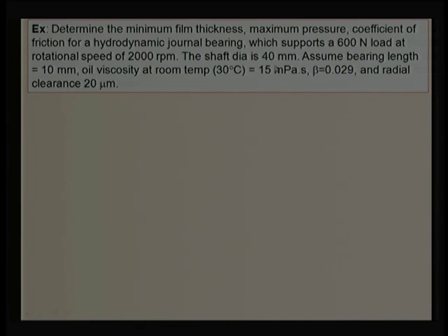That shows clearly the radius of the shaft is 20 mm, and clearance will be 0.1% of that, that is 20 micron. So, we are following that same scheme. The radial clearance is 0.1% of radius.